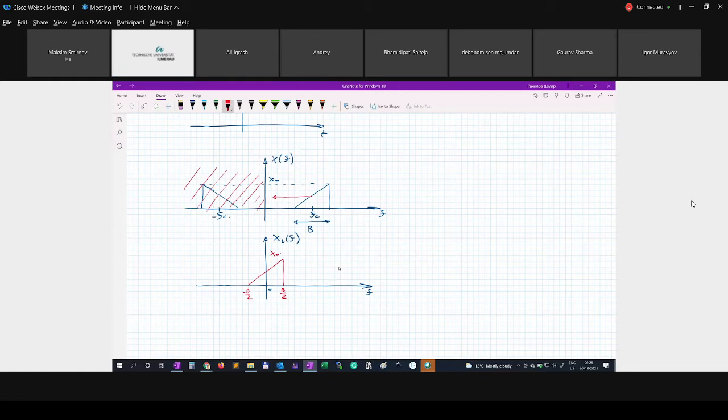So we multiply by square root of 2, because if we don't do it, the energy of the signal will be 2 times smaller. So times square root of 2. Okay, now this is our signal. This is our spectrum in a low pass range. And now we have to calculate the signal in time domain.